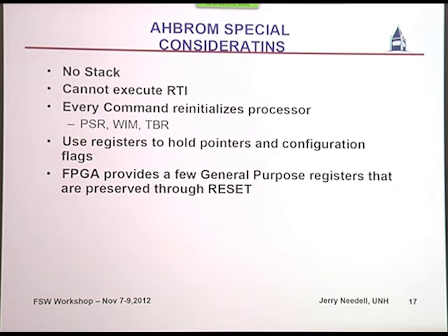When a command comes in, or any interrupt, you then process it, and then every command basically is like a new start. You reset all the parameters. So again, in the SPARC environment, we reset the window manager. We're only working in the first window of the SPARC. We're not using all the resources available, but we're using what we need. And then there are a few registers available to hold pointers and configuration flags, so you can actually do multiple-step commands.